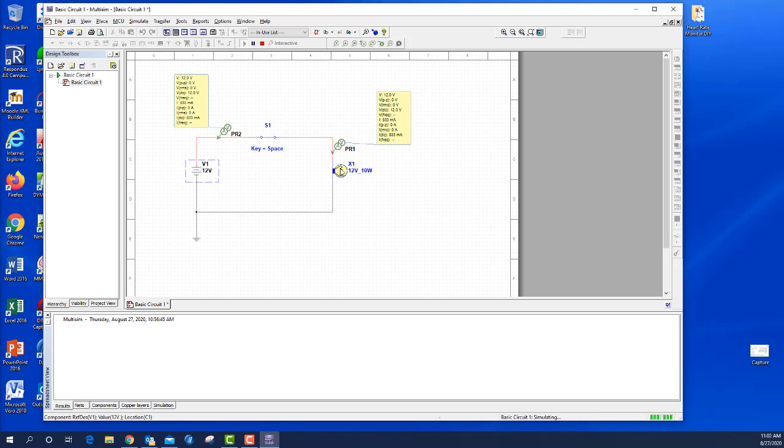And you're going to learn Ohm's law. That's coming up very soon if you haven't already started talking about it. If you know Ohm's law, then you can figure some of this out. If you don't know Ohm's law, you're going to learn it pretty soon, and then you would be able to calculate how much current a 12-volt 10-watt bulb should draw.